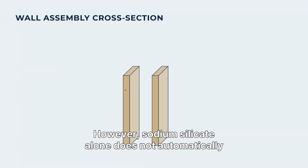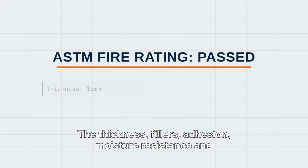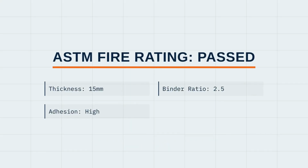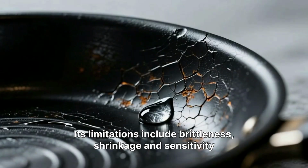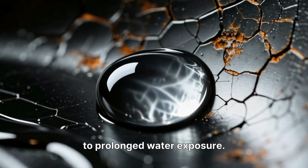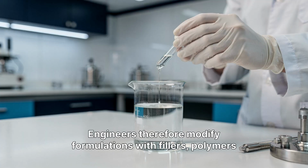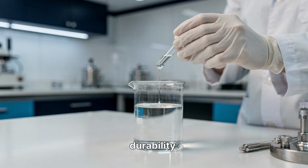However, sodium silicate alone does not automatically make a structure fireproof. The thickness, fillers, adhesion, moisture resistance, and complete tested assembly determine the actual fire resistance rating. Its limitations include brittleness, shrinkage, and sensitivity to prolonged water exposure. Engineers therefore modify formulations with fillers, polymers, or other silicates to improve flexibility and durability.